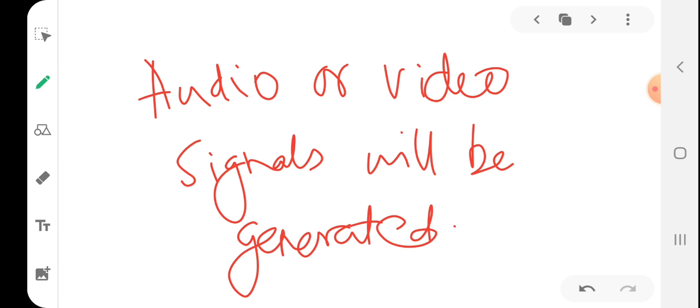Okay, so this detector has a filter that prevents contaminants and water from entering it. So only a refrigerant will enter this detector. There are filters used to prevent the entry of contaminants and water, so that the electronic leak detector can easily detect a refrigerant. If it is mixed with other contaminants and water, there will be some anomaly, because it is not pure. It can only detect refrigerants.